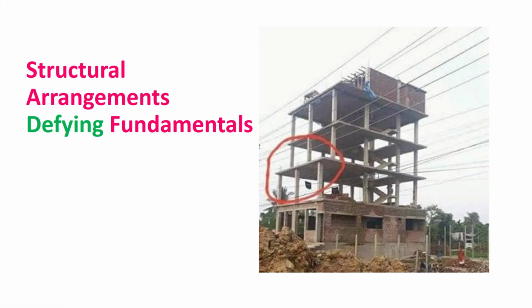Now what is wrong here? Can any participant tell what went wrong here? It's not a railway building, but maybe some other building, just to have an insight as to how the planning can go wrong. Now where is this particular problem? Column is resting, sir, on a slab, which should not be the case. Either it is onto the column or supported with the beam. Correct, but can you identify why he must have done this?